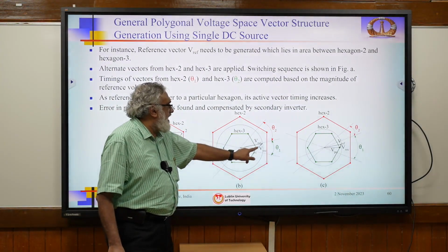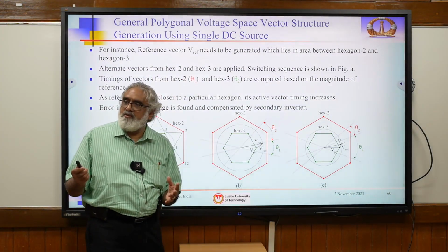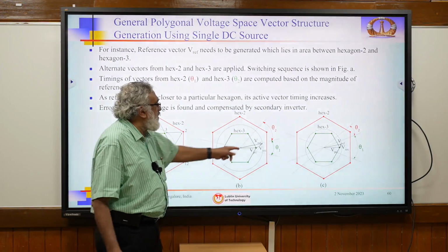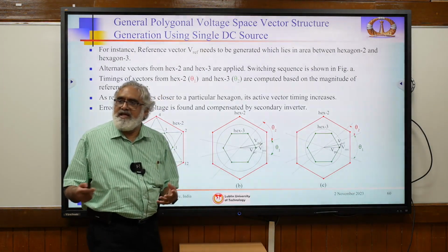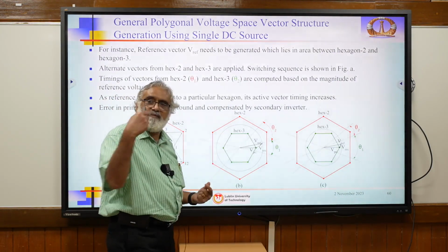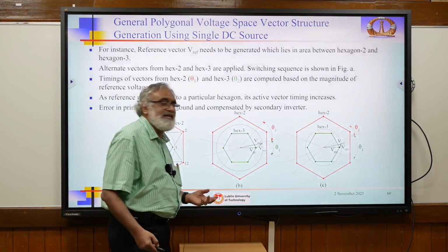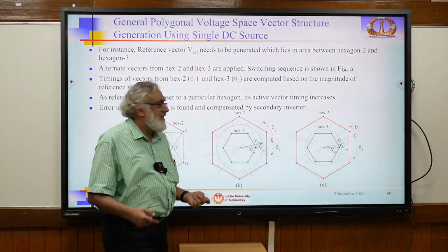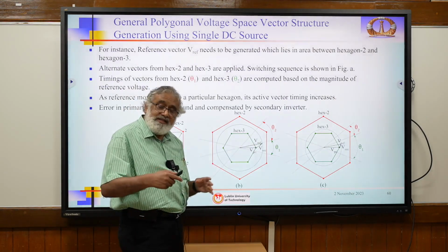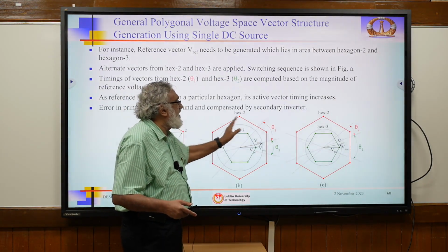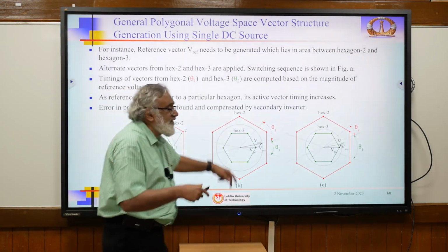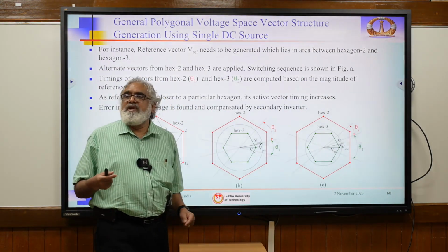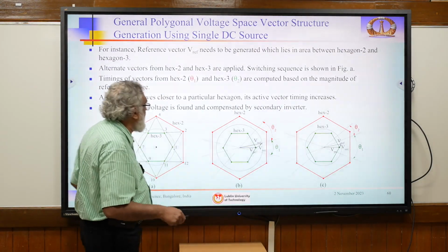When we switch this one and or switch one, we know the alpha beta value or VA, VB, VC. So by subtracting that value from here, we know the error value, what is the ABC. That error you feed from the other side. So what is the advantage? Error gets suppressed. What harmonics are suppressed depends on how much sampling you do. So with any number of samplings you do, shifting the error to the other side, we can suppress the harmonics. That is the idea here.